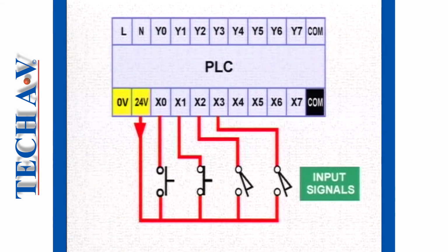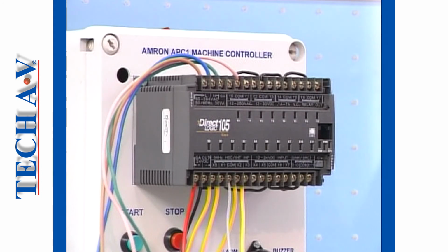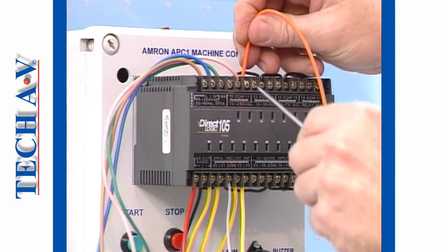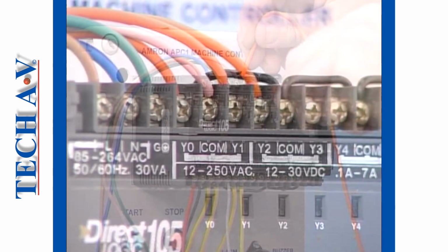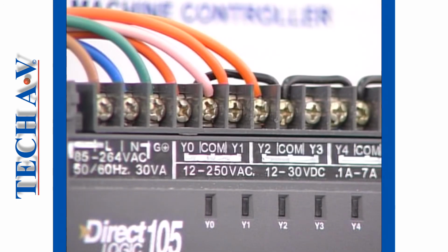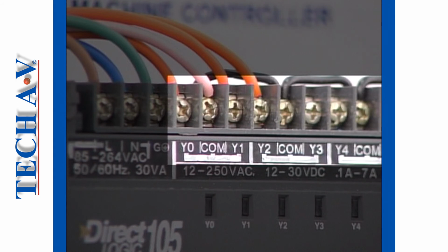This typical wiring diagram shows how the input connections to the PLC are arranged with one input terminal allocated for each external device, and a common return line to complete the circuit for each input. In a similar way, working devices are connected to the PLC through an output interface or module. And just like the inputs, each output point has its own unique address location, so that the processor knows where to direct its output signals.